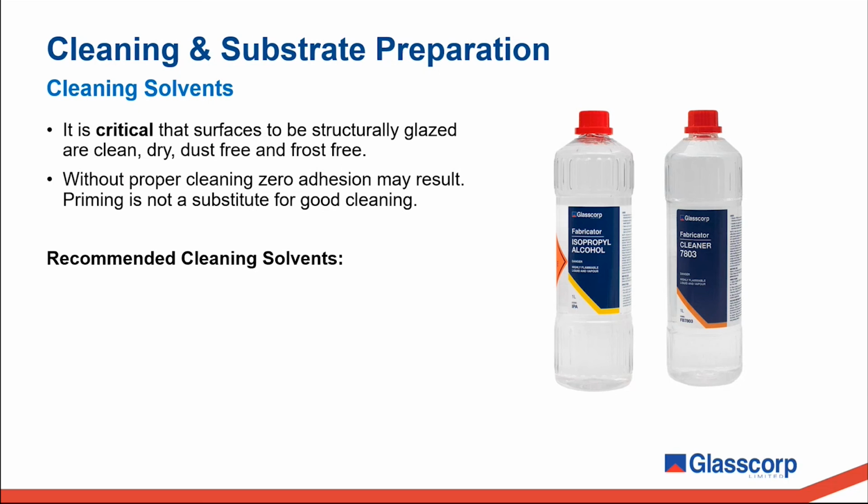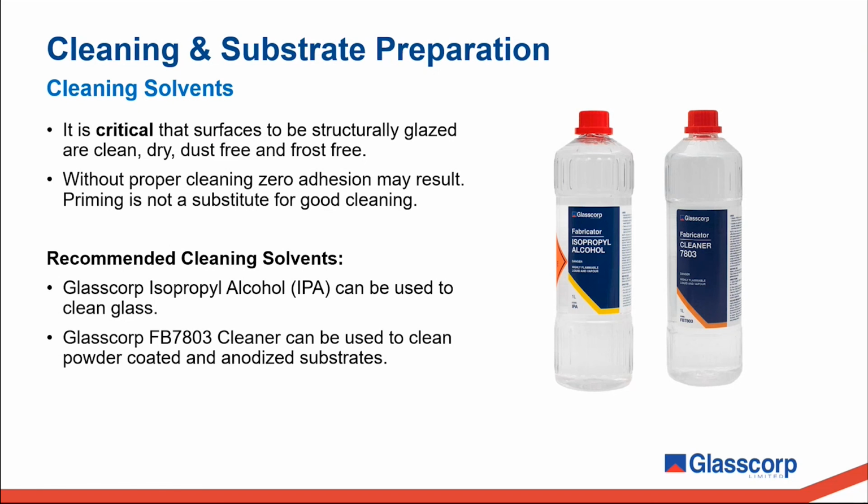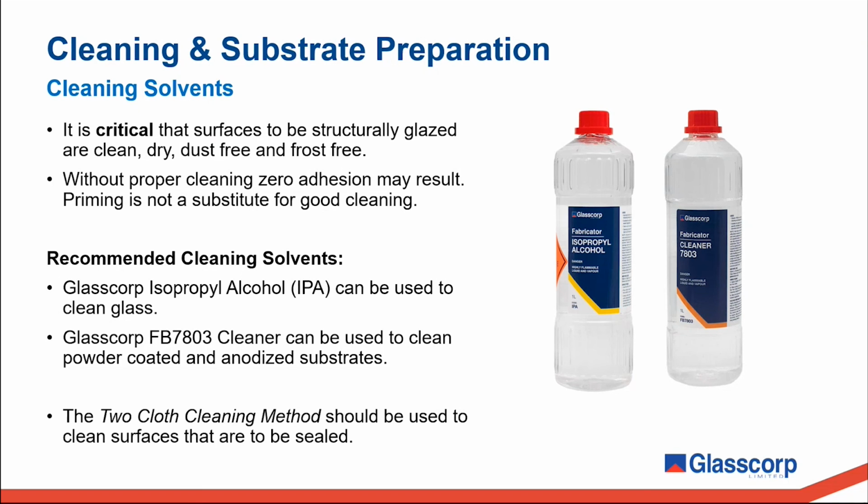Recommendations on the appropriate cleaner to be used will be detailed in the adhesion test report issued from Dow. From our own experience, we recommend isopropyl alcohol or IPA to be used to clean glass, and Glasscorp FB7803 cleaner for powder-coated and anodized substrates. We recommend using the two-cloth cleaning method on all surfaces where sealant is to be applied.